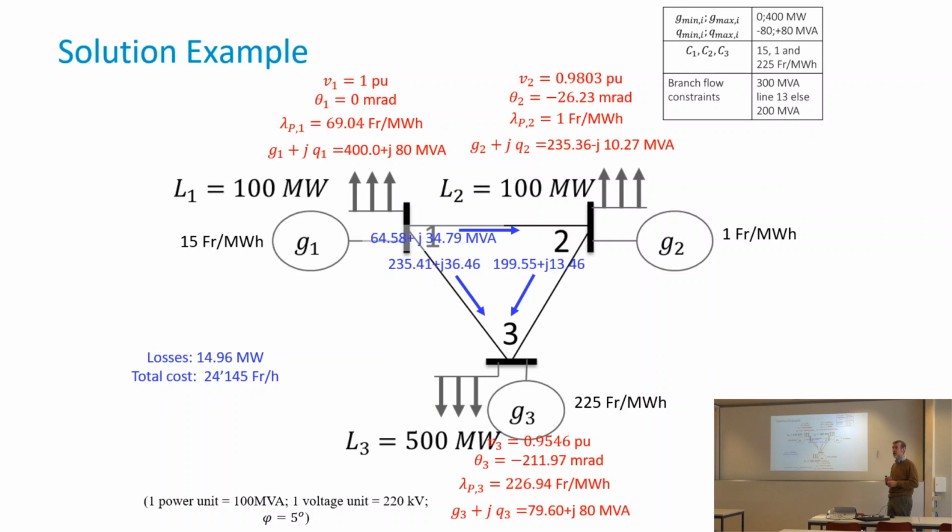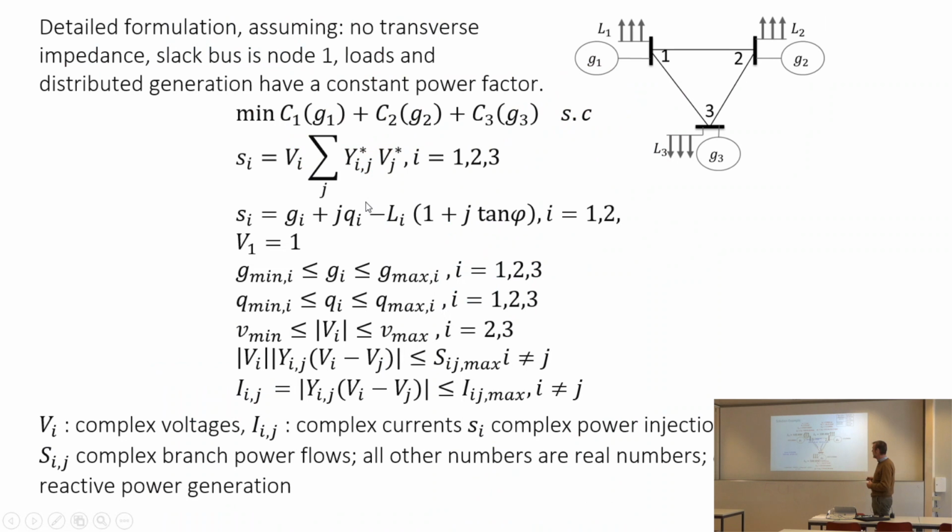So as an operator of this grid, and as an optimizer that tries to minimize the cost of the grid, you will automatically try to reduce the amount of apparent power. And there is reactive power from 2 sources. There is one generated from the loads.